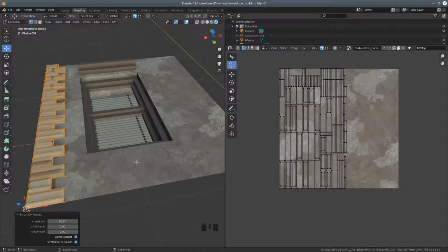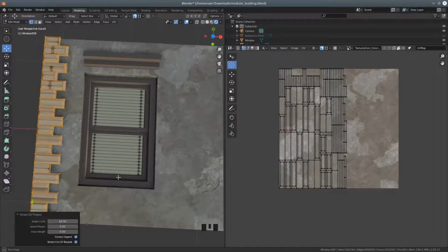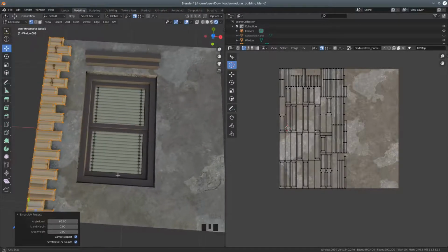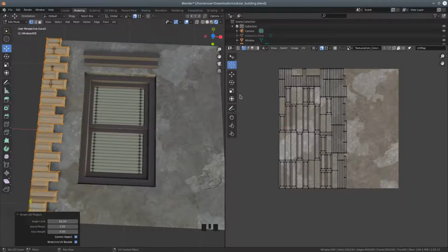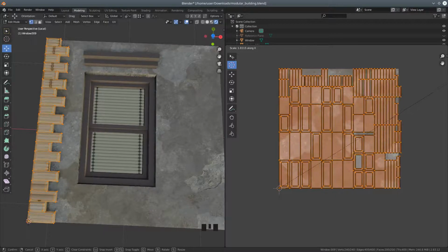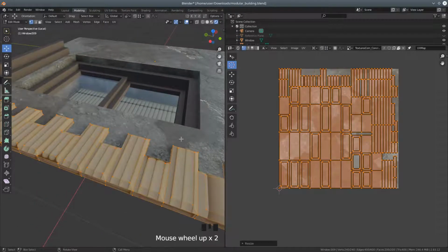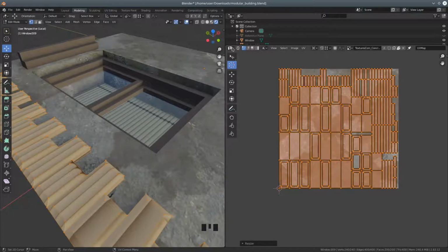Stretch the UV bounds, that looks okay. Although there's some rather strange things going on there. But what we can do is put our corner point down here in the corner. We can then B to box select that. Let's take that off. Let's scale it on the 2D cursor. Let's go scale it in the X direction. We'll just stretch that out a little bit. For some reason that has got a wrong texture in there, so we'll just look at that.